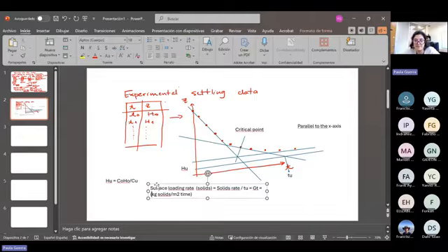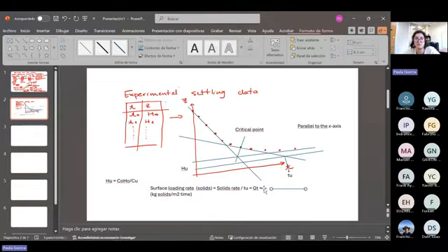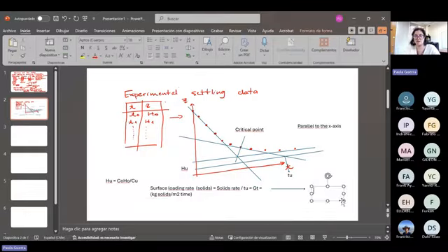And finally, this is the parameter that we're going to use to size the settler. But I'm going to do it through an exercise, so it's a little more clear than what I'm saying now. This is what you finally use to calculate the area of the thickener, and in consequence, that's what we can use to calculate the diameter.